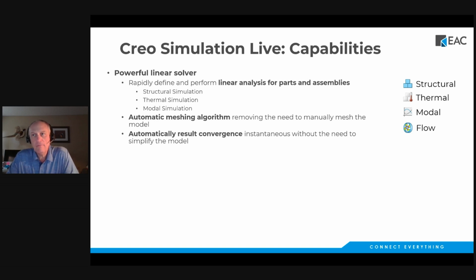If you're familiar with FEA in general, you're probably familiar with the different mesh types, whether that's traditional H-type elements or the adaptive P-type elements in Creo Simulate. We're doing something a little different here, where we're discretizing the model and then using the video card to do some parallel processing on the volume that is included in the part or assembly, and then doing our simulation on that. So we don't think in terms of mesh refinement. There are capabilities to allow me to control the speed and accuracy of the results. Basically, it's just a slider that allows me to toggle between the different ranges of the solution that I want.